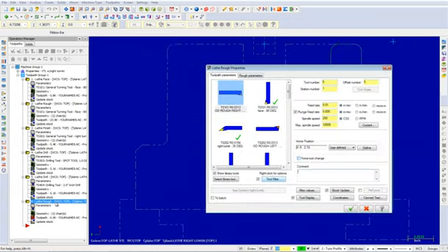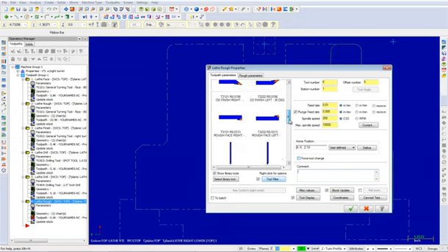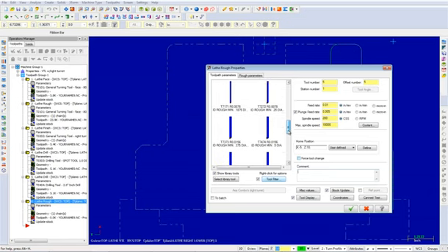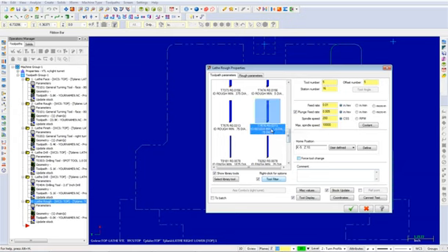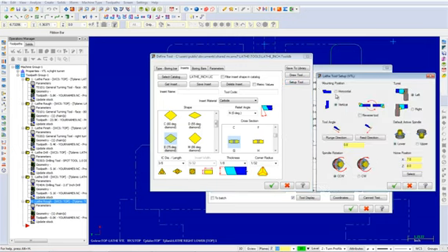In the Toolpath Parameters tab, select the ID Rough Min 1-inch diameter with an insert of 75-degree tool and right-click on it and choose Edit Tool. Pick the Setup Tool button as shown and change the turret to right. From here, select the OK button twice and input the comment, rough and finish the ID.